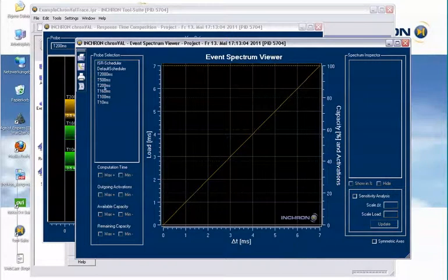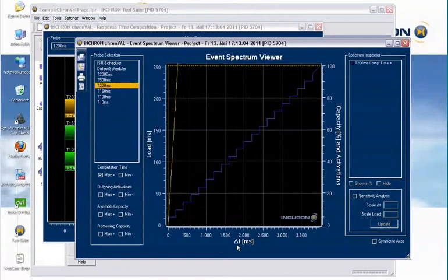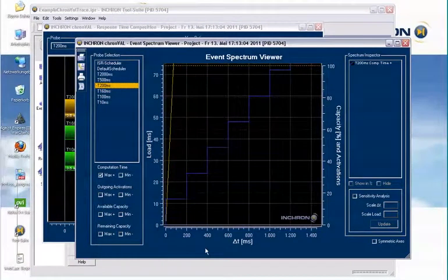So if I take a look here at the 200 millisecond task, and let's say what's the maximum computation time of the 200 millisecond task, we see a kind of step of a ladder or stairs here. And what does this show? If I zoom in a bit, it shows that in an interval of 200 milliseconds, or a bit lower than 200 milliseconds, there will be maximum the request for a computation time of 12 milliseconds. And minimum at 200 milliseconds, there will be the next request for computation time, and it will request another 12 milliseconds, so we're here at 24 milliseconds computation time.